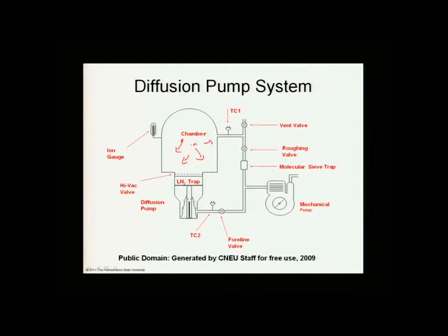This must be low pressure, means high vacuum. This must be high vacuum, or maybe even bordering into the ultra high vacuum. This is your oil jet down here. Here's your liquid nitrogen trap to try to stop any oil molecules from getting up here. You want to freeze them. This is our glass of cold water idea, where water vapor sticks on the side.